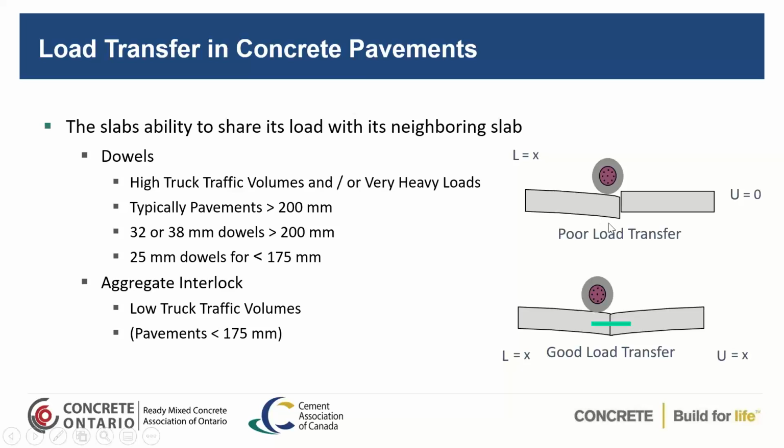down. That'll cause a suction in this area, and if you have a source of water in the fines, you'll actually get some of the pumping through the crack or through the sides of the pavement, and you'll get a gap underneath. And that's why you get sometimes in older concrete pavements that weren't fitted with dowels originally, that thumping noise that you hear on the concrete. So load transfer is extremely important.